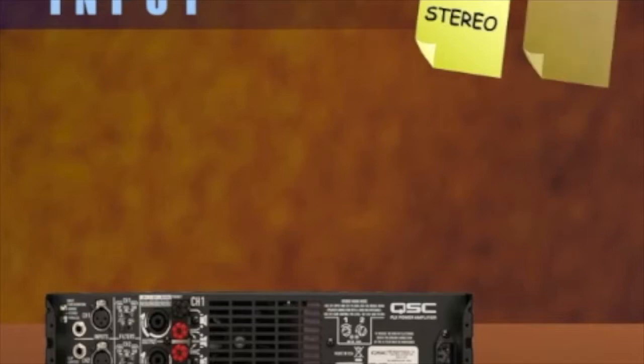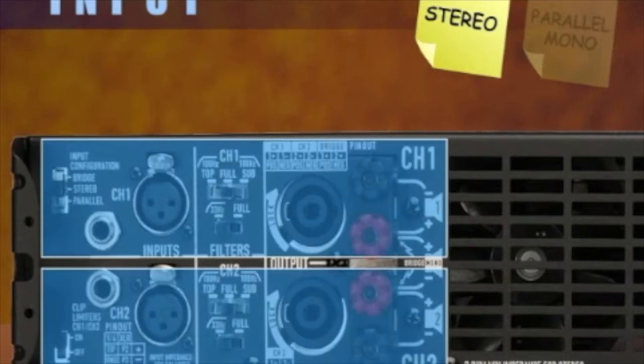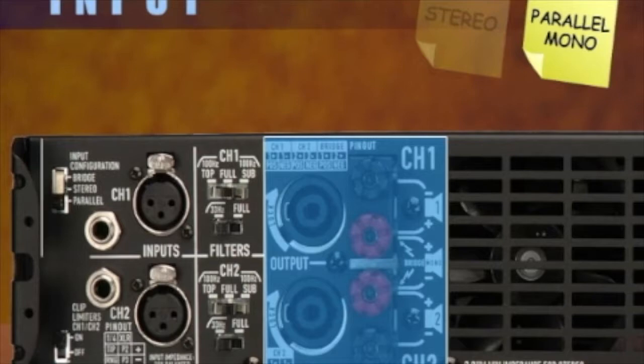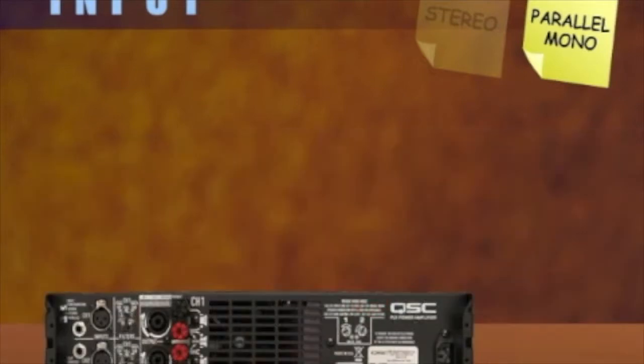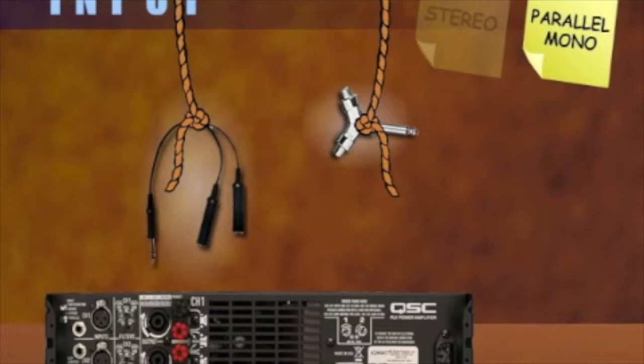There are two basic input configurations for a two-channel amplifier, stereo and parallel mono. Stereo mode implies that each channel will receive a different input signal. In parallel mode, each amplifier channel receives the signal connected to input 1. Parallel mode eliminates the need for Y cords and adapters when a common signal is required to feed both amplifier channels.